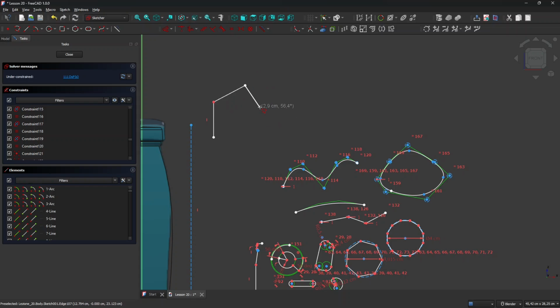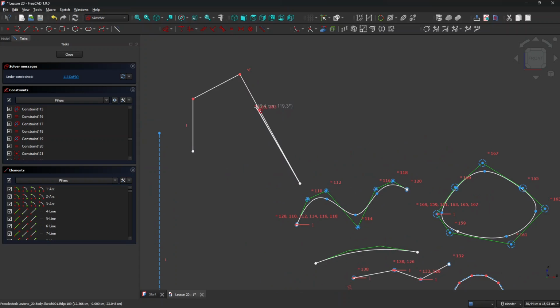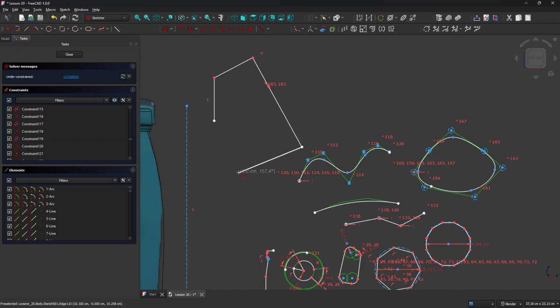But if I press the M key, M as Milan, it's going to turn this into like a corner. It's going to be a 90-degree corner. So I can click, and that's going to create, you see, a perpendicular constraint right there. Now again, I'm going to press M, and a second time, I'm going to press M again, and now it's doing something like this. So let me go down here. So you're basically creating a tangent or collinear constraint.